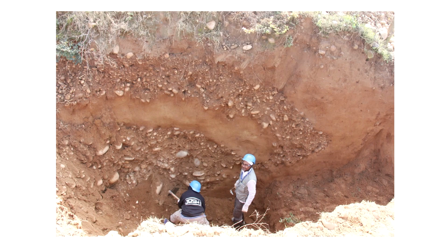Now, this is another picture of a trench, again in Punjab, now with proper helmets and all that. But cleaning is very important. You may have to soil yourself cleaning the trench properly, because you need to expose each and every unit. That is important for mapping and also for understanding the deformation pattern, as well as the events, the number of events.